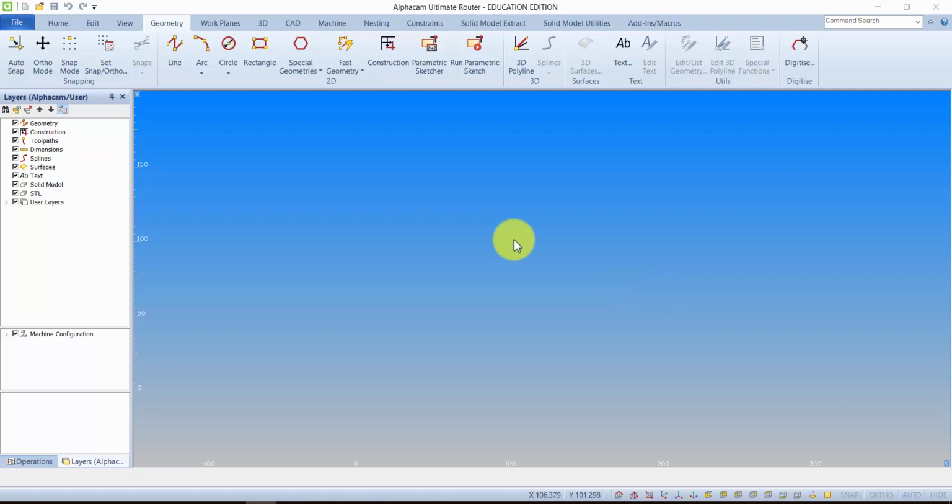Now opening up a new file in the software, looking at the drawing that you can either take a screen grab of from previously or download the notes from Learn Online, you'll notice that the logo begins with a horizontal line across. So for convenience, I'm going to start at 0, 0. So 0, tab, 0, enter. That's the first point. And the line needs to be across 240 millimeters. So that's 240, tab, 0, enter.